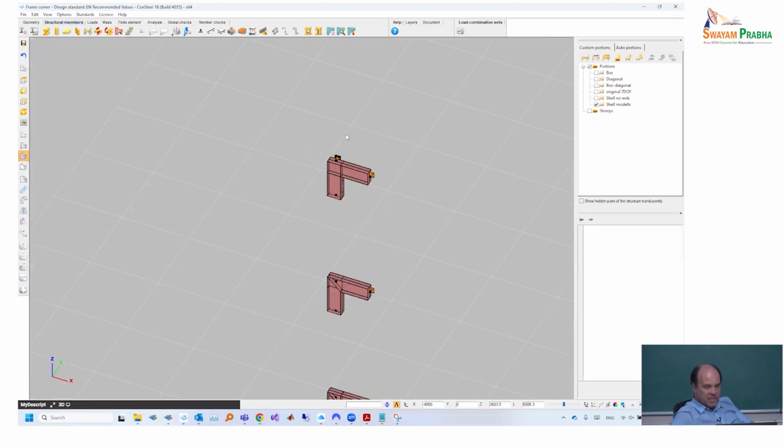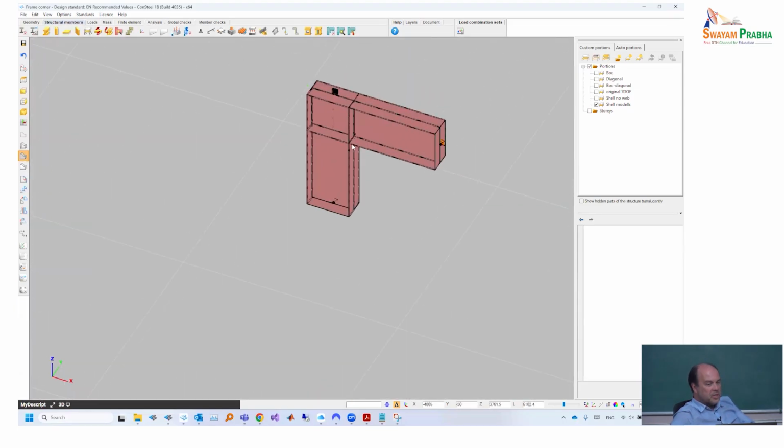Yeah, here is better visible. For the first one I used this sort of box configuration, which is very often used for metal buildings, where the flanges are continued into the adjacent element, and finally the web panel will be framed by flanges and stiffeners. Of course, some of these plates are stiffeners welded into the one element, others are end plates or the flange of the element. So it doesn't matter, but they are all framed together.